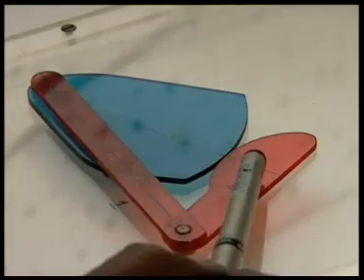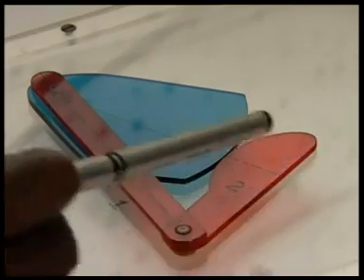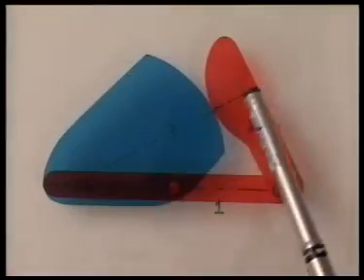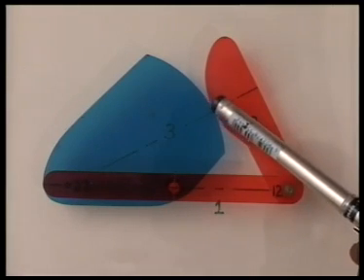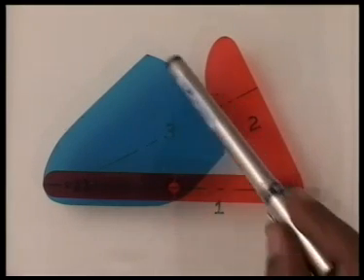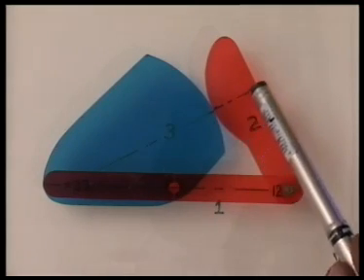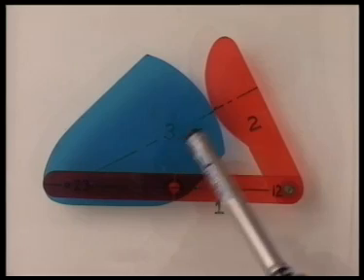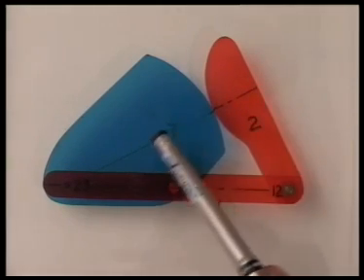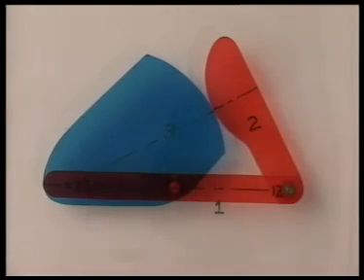Now, the relative instantaneous center 2,3, I know, must lie along the common normal at this point of contact. This is a general higher pair. We have already discussed that in case of a general higher pair, the relative instantaneous center, in this case between body 2 and body 3, that is I2,3, must lie on this common normal.